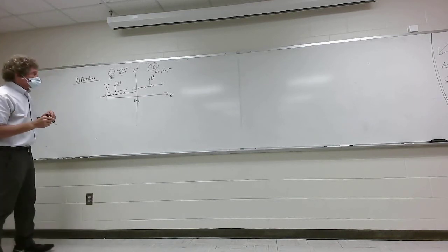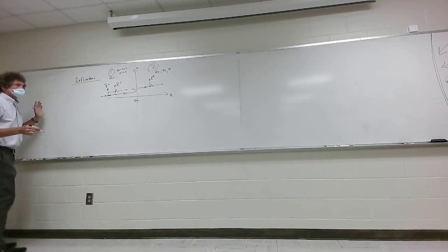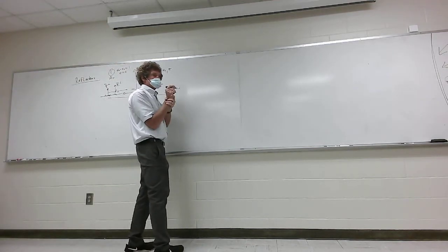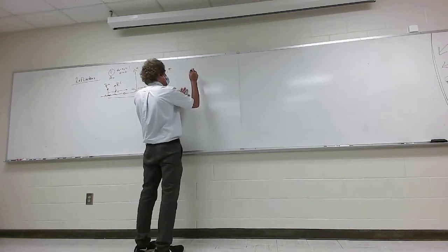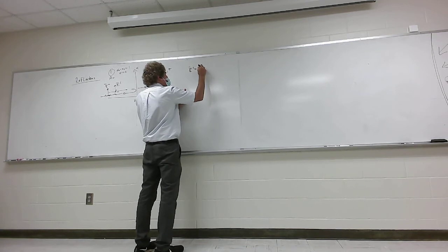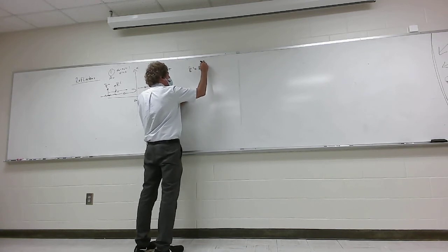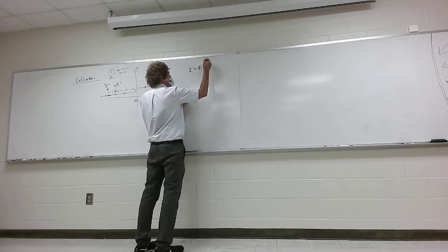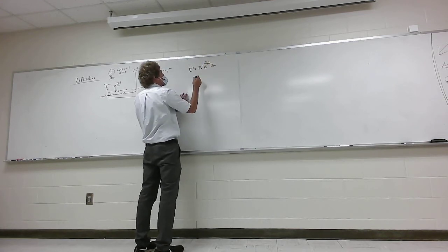Okay. So when I look at this, I'm going to use the standard convention Dr. Wentworth does over here. I'm going to say the incident field plus the reflected are in region 1, and the transmitted field is in region 2. So when we look at this, the incident field would have the form of some E naught incident, e to the minus, and I think he uses gamma, but it doesn't matter. E to the minus gamma 1 z, ax.